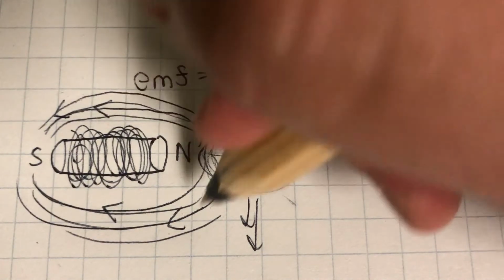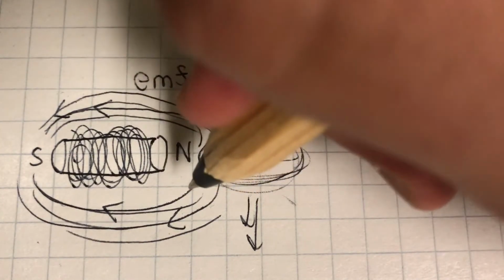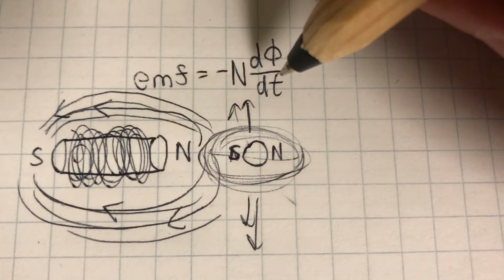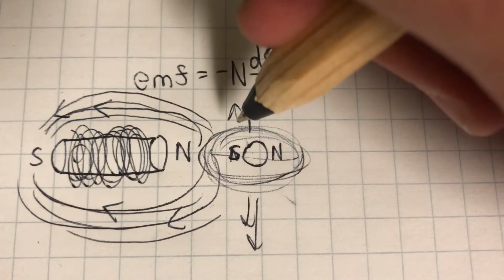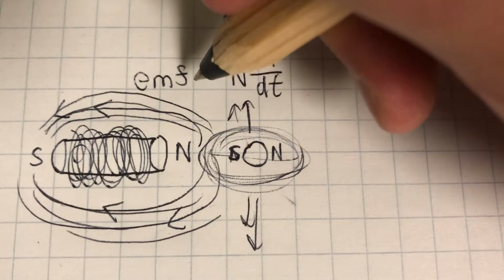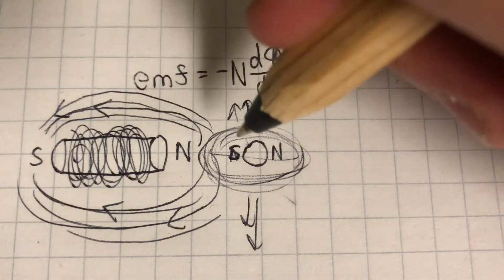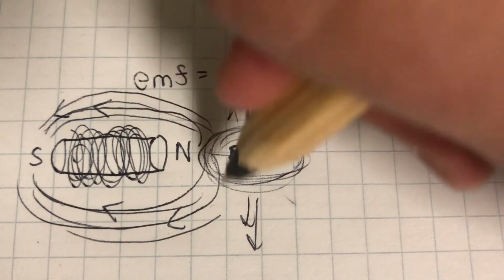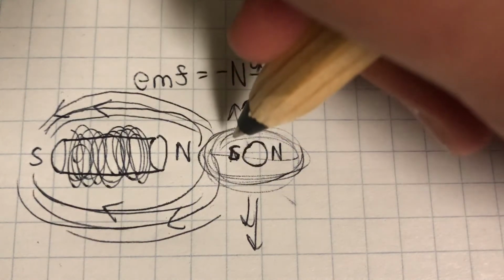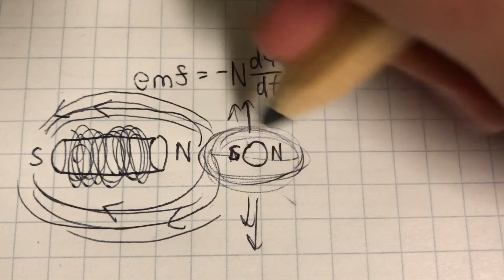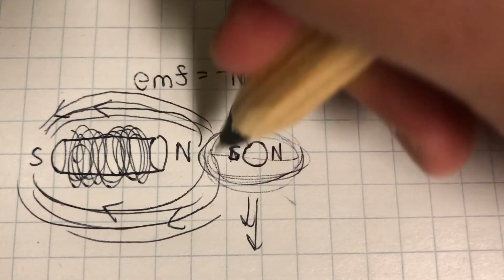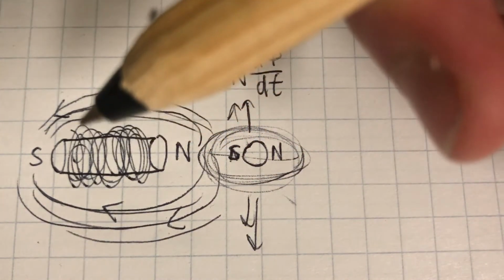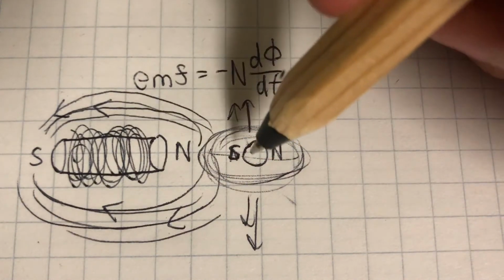This oscillation is changing the magnetic flux of the magnet, and because of the change in flux, we're going to have an induced voltage, and hence an EMF. And that is where the voltage is coming from for an electric guitar. It is the change in flux due to the vibrations from the oscillation of the string that affects the magnet's flux. And again, this is only one magnet, so we're going to have 5 other ones, and they're all going to be doing the same thing depending on what string you play.